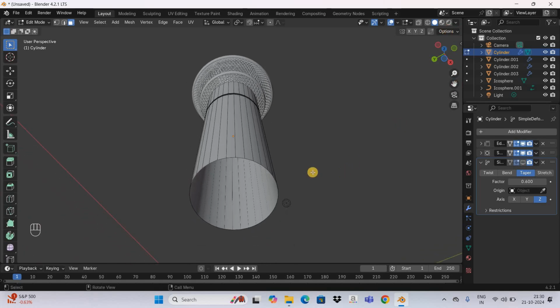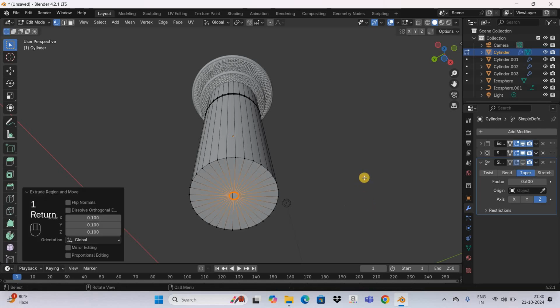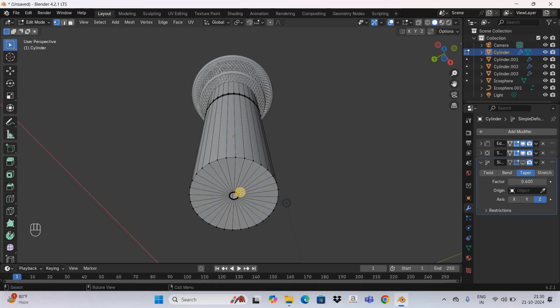in the bottom. Now what you need to do next is select the vertex selection mode and now select all the vertices which are present right at the bottom. And now you need to actually press the letter E to extrude and now press the letter S to resize and now simply enter 0.1 and now press enter. And so as you can see, what we have done is we have created a small circle for wire input, and this pretty much actually completes our modeling of the microphone.